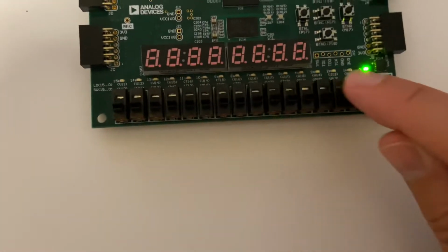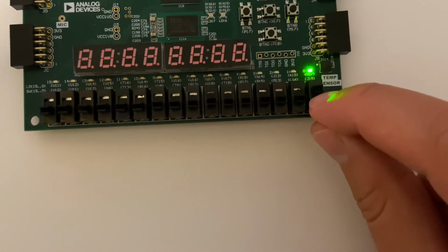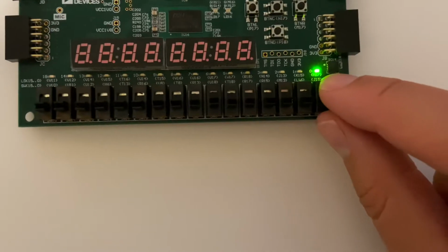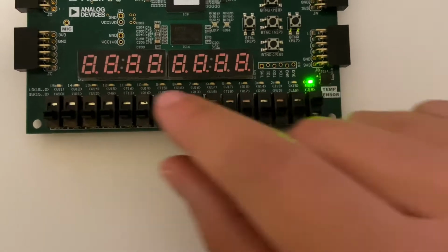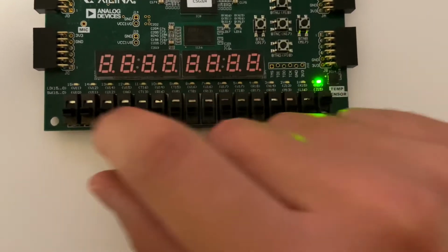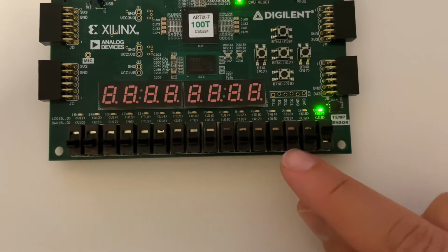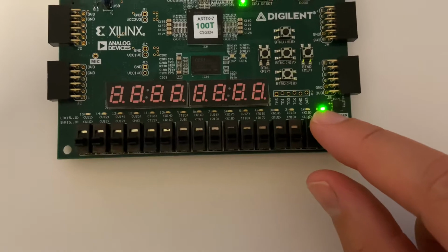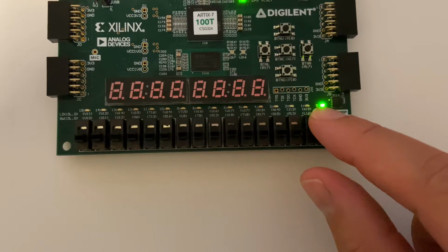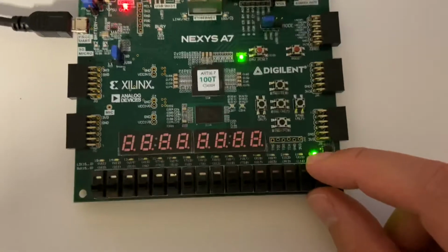The I/O that we will be using are all 16 LEDs on this bottom row right here. And then we have this switch right here, which when high is just going to hold LED 0 high. When I pull this low, it's going to start bouncing from LED 0 to 15 and then back from 15 to 0. And then we have these 5 switches right here, and these control the delay of LED switching from here to here to here to here, etc. So we'll see that in action right now.